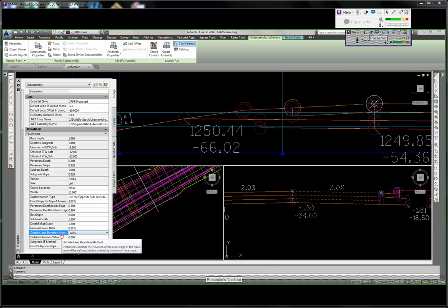Now, I don't have a profile to target it to. Basically, just suffice it to say that in a lot of cases, if you do have an assembly that's going to a profile, that is going to be the usual suspect you should watch for. You see it a lot in intersections in particular, because if you don't have it set to profile, the intersection tool doesn't know the switch is in there, so it doesn't know to turn it on, and even though the intersection thinks it's going to whatever percent it needs to go to, it's stuck at 2%, and you get weird connection points.